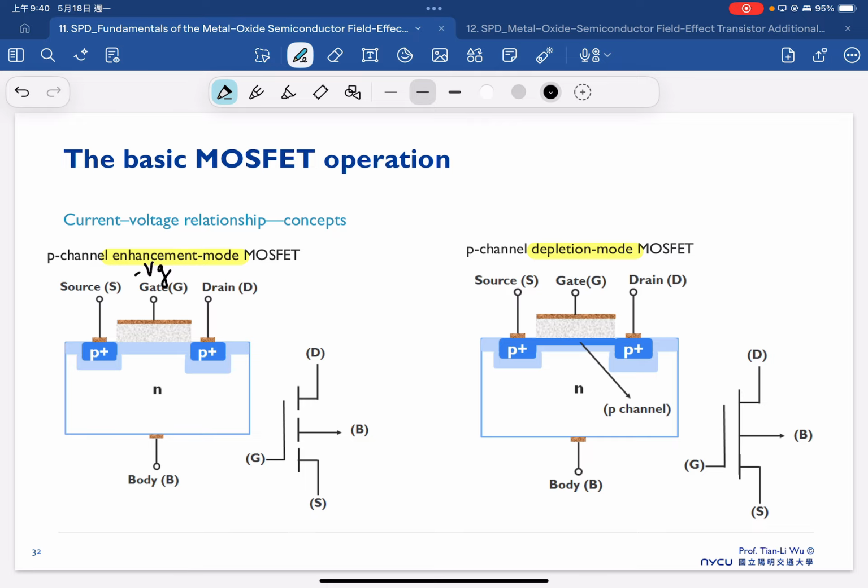to invert the holes. So we need to have the holes inverted in the channel, because the substrate is N type. So therefore we need to invert the hole. That's why we need to apply the negative gate bias enough to induce a hole inversion in the channel.